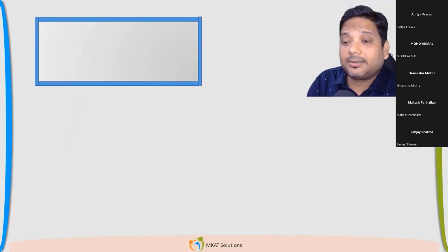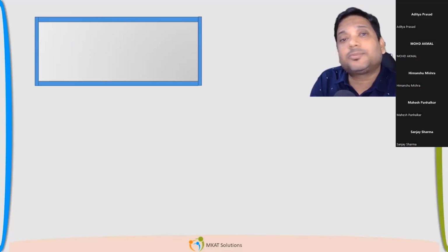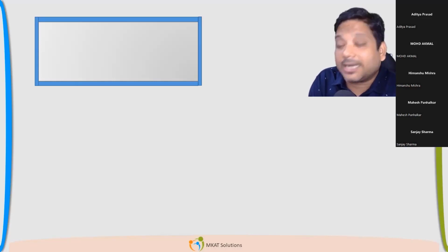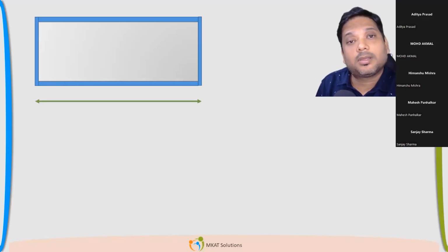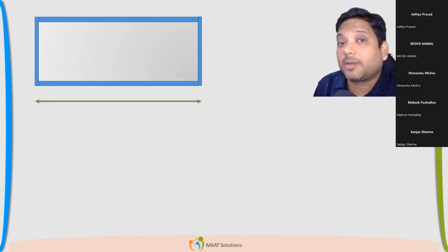Yes, because you can see that. See, it's very simple, it's supporting both the ends. There is support available. Okay, so line of support is nothing but the distance between the line of support, that is the L. So here line of support exists at both the ends. Okay, so my length will become end to end. This is my L for external pressure calculation. This is very easy. You can understand it also.